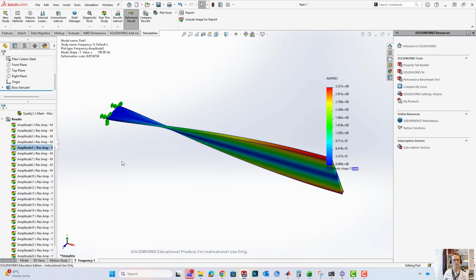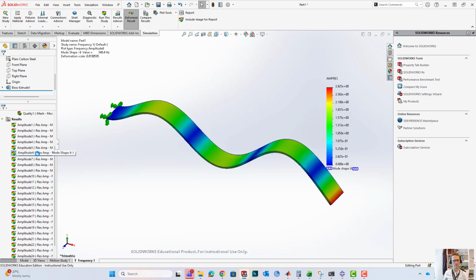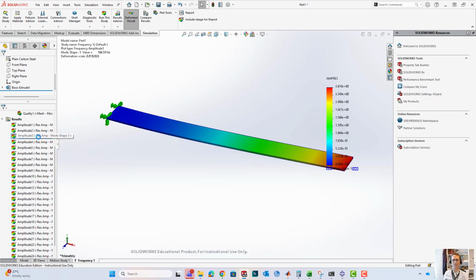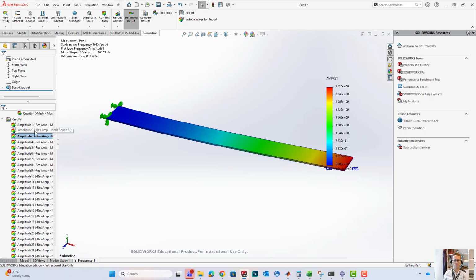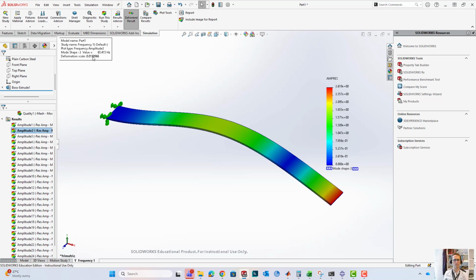That's a torsional mode. That's the fourth bending mode. So that frequency is 384. So we're collecting these frequencies to compare with MATLAB. 177.6. So you've got to watch out for those other frequencies that are for shapes that we're not predicting in MATLAB in the comparison.